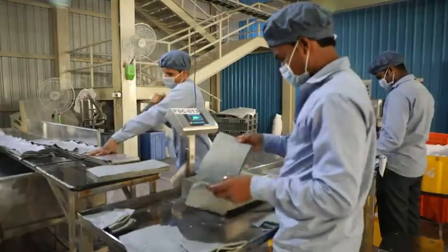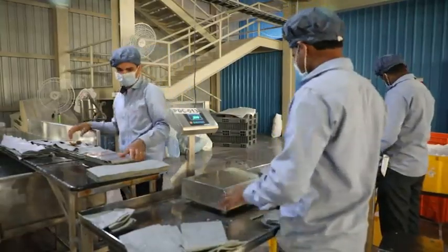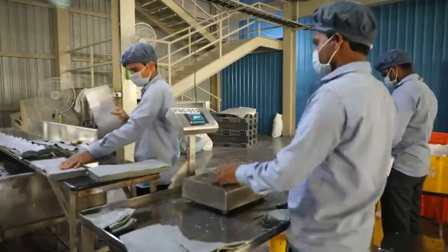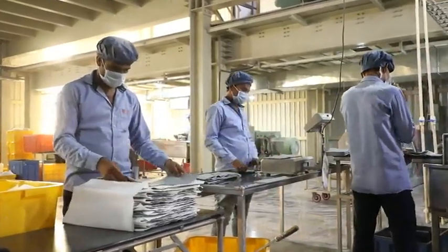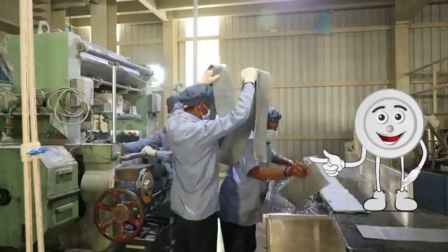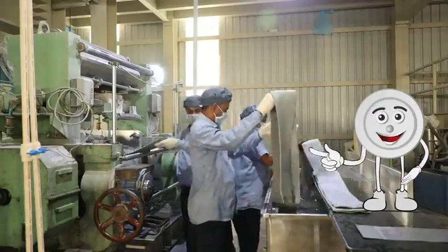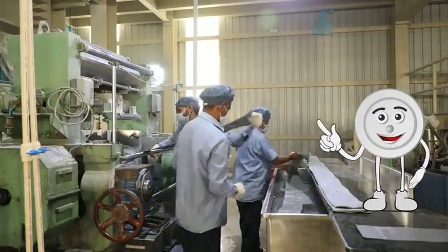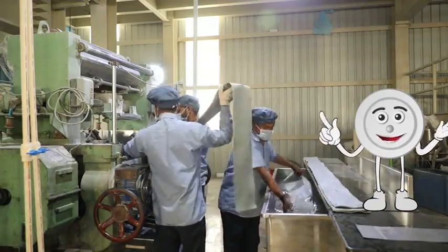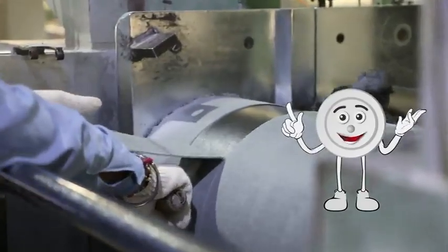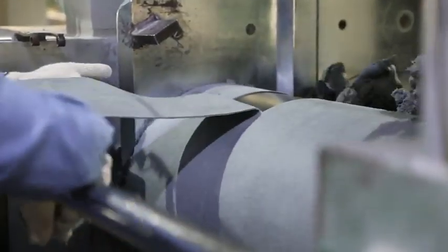The next step is cutting the strips and weighing them before moving to the next step. The strips are then cut and weighed as per the programmed loading weights. The rheometer machine, a moving die rheometer, is then used to measure the viscosity and rheological properties of the compound generated after kneading or intermixing.